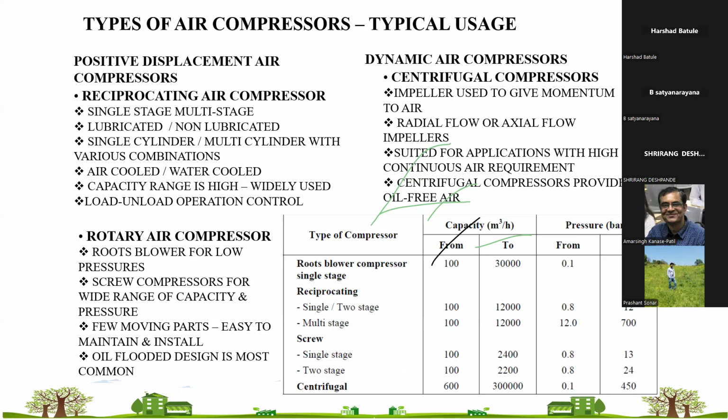If you see the example of it, positive displacement compressor and dynamic air compressor, we will go one by one. An example is the screw compressor, which is widely used, a normal screw compressor which has 7 bar pressure. Your suction air comes into that particular compressor, and between the screw elements the air is compressed, it reduces the volume and increases pressure by passing through that particular screw element. So that is the virtue of a positive displacement compressor.